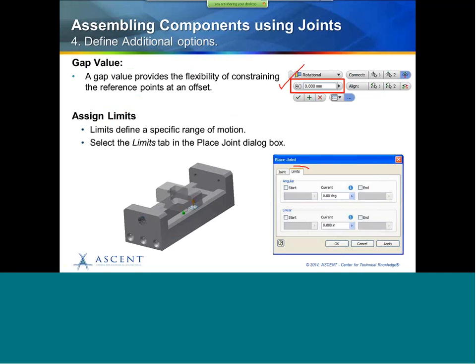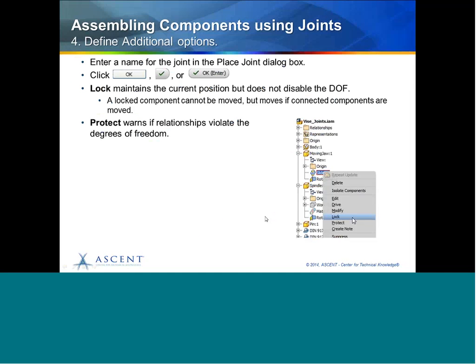And then we mentioned briefly the ability to set limits. So in this example here, if you look at this little animation I have, that slider in the preview animation is only sliding within a few inches of the assembled position. However, once we finalize it, we could drag it through, and interference is not considered. So limits could be set here, where you could go in and set the linear control, your start and your end point. And then you can complete the joint.